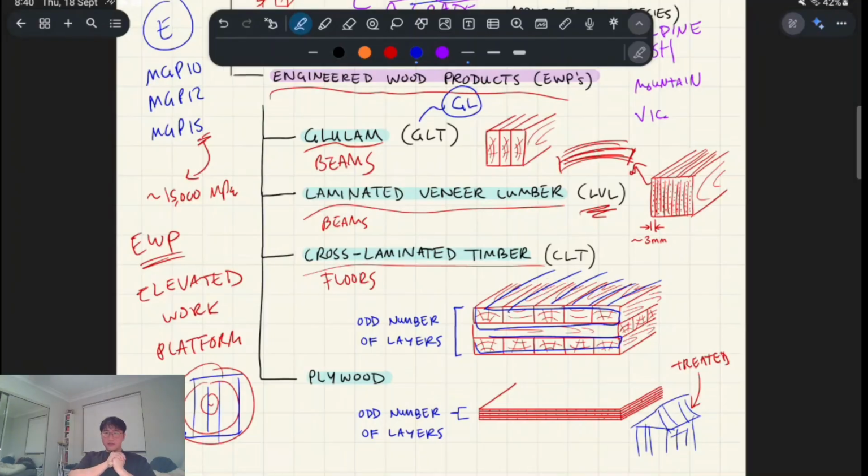And basically, if we bend in this direction, parallel to the grain, you basically have stronger properties. So the longitudinal direction runs this way, and there's 2 layers of that, and then in the minor direction, we have longitudinal layers running that way. So that's the minor direction.